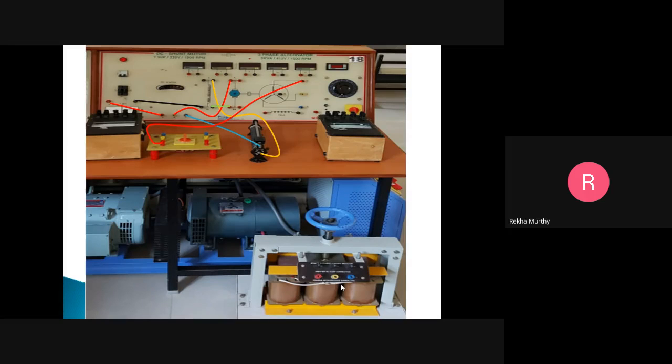Coming to the alternator, one end of the TPST should be connected to U, V and W. The output of the TPST for U should be connected to the wattmeter M, and MC should be shorted, and L should be connected to one of the inductive load. The other end of the same V connection should be shorted together, and the interconnected point should be connected to the ammeter, and the other end of the ammeter should be connected back to the V position. And the output of the other side of the TPST should be connected to M, and MC should be shorted. L is connected back to the load.